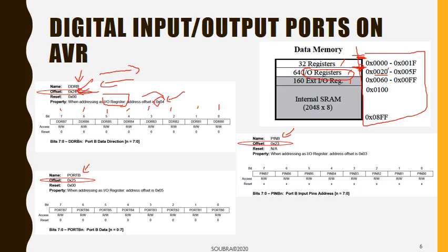One last thing that you should notice is the reset value. So this is the value upon reset, and you can notice it's all zeros. Why should we have some fixed value here and not a random one? And this is again from last lecture, we need to have a stable state. So it makes sense to have zeros here, so we can know that this is where we're starting, and we know what to expect as a behavior.